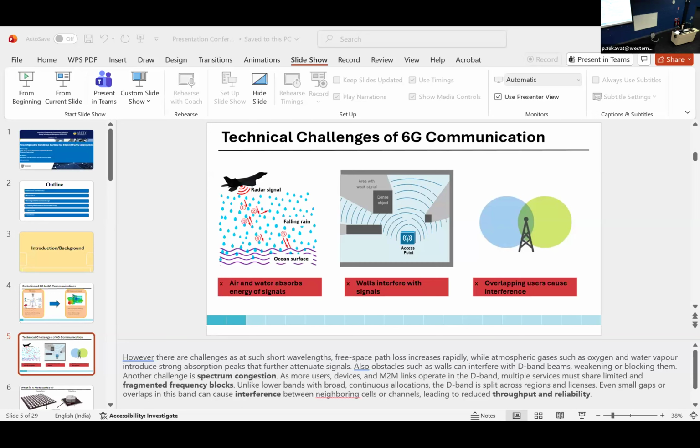In the analysis setup, the metasurface was analyzed under the full D-band spectrum, and a linear frequency sweep with 100 megahertz step size was used to allow fine spectral resolution around each resonance. And then only the transverse electric and transverse magnetic normal modes were excited. The output analysis focused on the S parameters, as at such short wavelengths, the D-band spectrum is hard to observe with far-field tests. These coefficients can also help find a stop band.